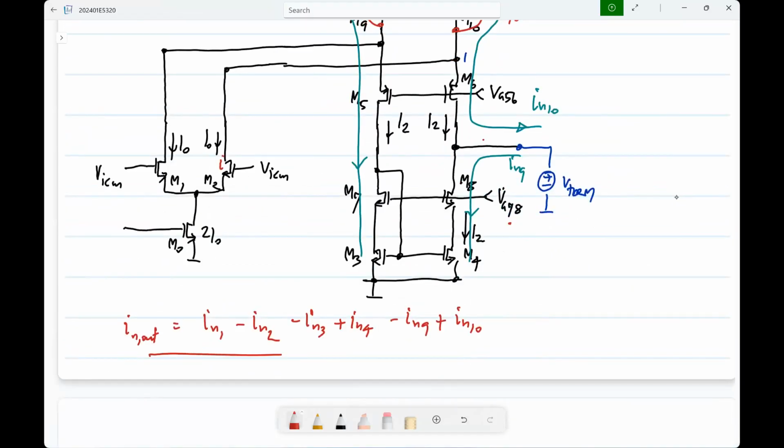So now basically this adds both to noise and mismatch. Again, remember M9 and M10 are larger transistors. They have more current. They are likely to have more GM. So that means that the noise current will be higher, because the noise current power spectral density of a MOS transistor is proportional to GM. And the same goes for mismatch. So in that way also, this folded cascode is worse, because you need these additional biasing sources to bias the cascodes, and they will contribute to output conductance, noise, and mismatch.